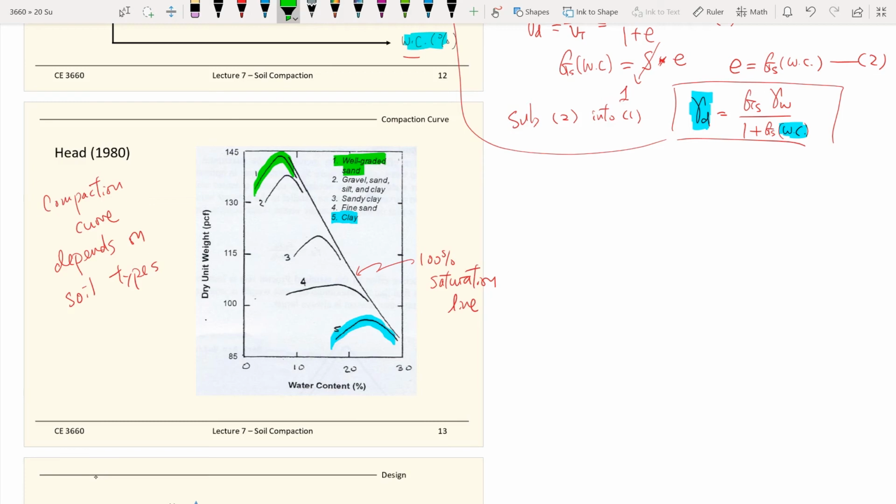In the other case, for example, you have a dam or levee to build. You want to slow down the seepage of the water. Then it won't make sense to use gravel as the fill material for your levees, because the water can freely drain through it. You want to slow down the seepage, so it makes sense to use clay material. So you work with construction management and specify the fill material to be a clayey type of soil. With your geotech understanding, you help do the design and specifications.